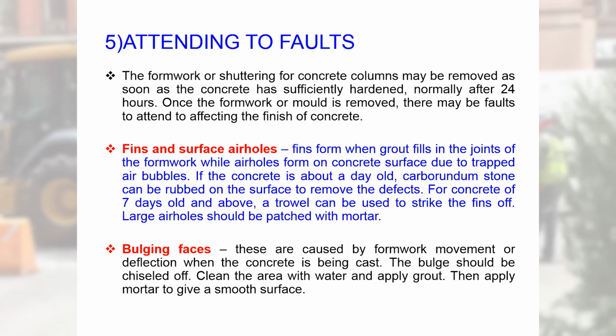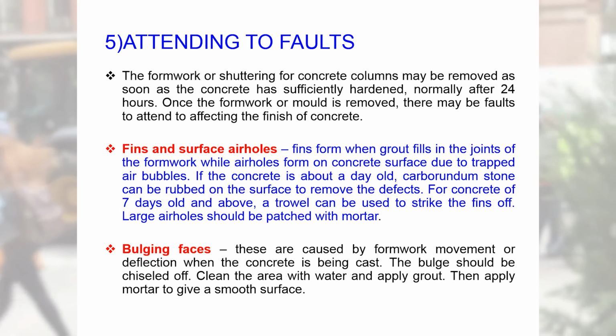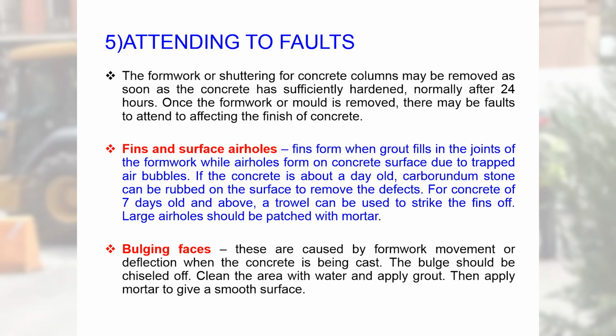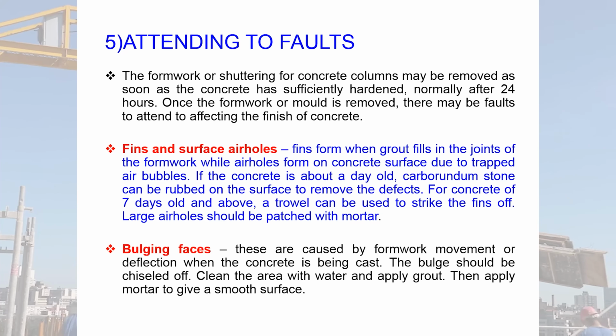Bulging faces. These are caused by formwork movement or deflection when the concrete is being cast. The bulge should be chiseled off. Clean the area with water and apply grout. Then apply mortar to give a smooth surface.